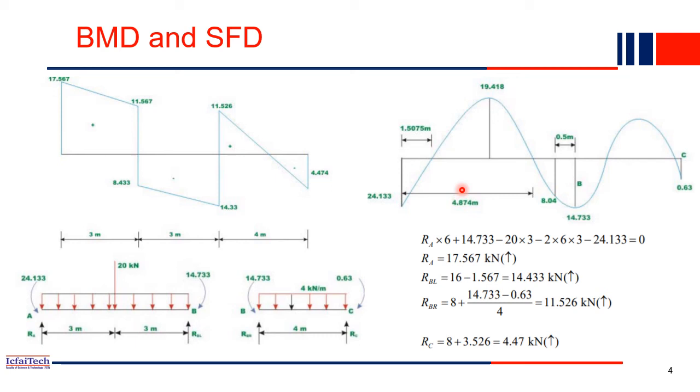So like that we can solve using the slope deflection equation very easily. You can solve the indeterminate structure and easily draw the shear force and bending moment diagram at any element. We have to use the slope deflection equation, then use the compatibility equation to find the unknown kinematic degrees of freedom, then substitute into the equilibrium equations, find all the reaction forces, and then draw the shear force and bending moment diagram.